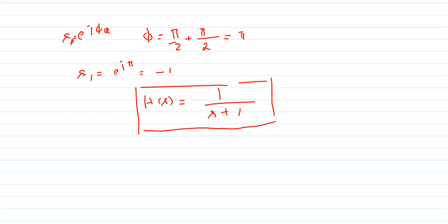This normalized transfer function has to be converted into a high pass filter first. To convert this H of s into a high pass filter, we have to apply the transformation s as omega c by s. What is the cutoff frequency for your high pass filter? 7265.